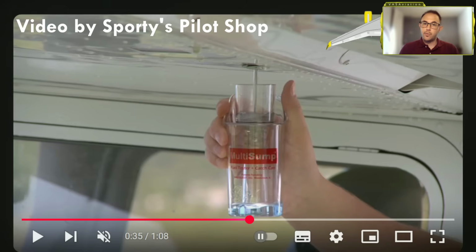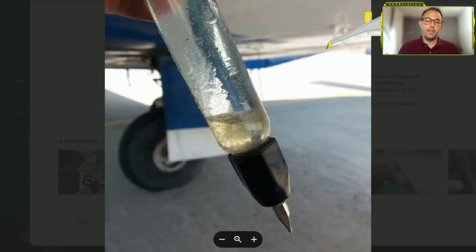So it's really important that we drain the fuel tanks before every flight, or at least before the first flight of the day. I have some real photographs here from my flight academy. I think a couple of those photos were taken by myself. This is the difference, and you can see the contaminants there at the bottom of the drainer. We don't know if it was water, I don't remember, but you see there's a difference in color there. It could be dirty water or something, but you see the difference there.